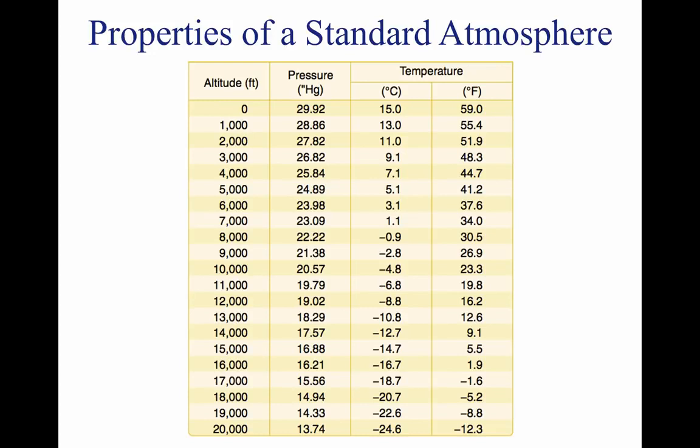Since all aircraft performance is compared and evaluated with respect to the standard atmosphere, all aircraft instruments are calibrated for the standard atmosphere. Thus, certain corrections must apply to the instrumentation, as well as the aircraft performance, if the actual operating conditions do not fit the standard atmosphere. In order to account properly for the non-standard atmosphere, certain related terms must be defined.